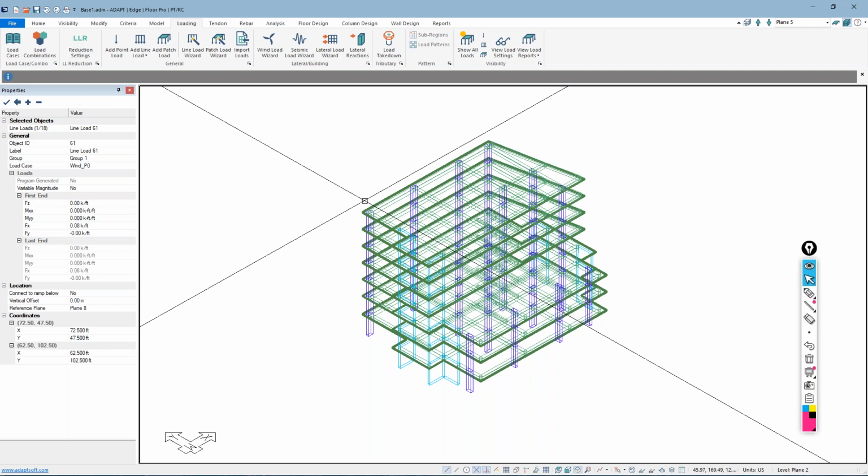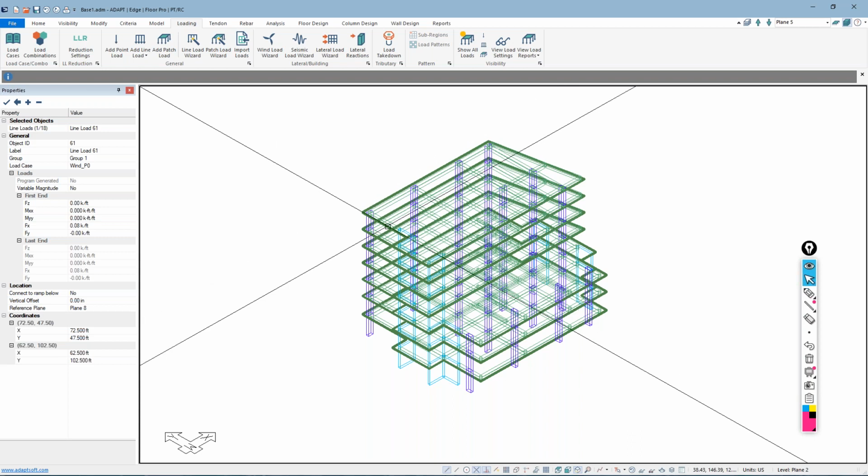Once you set up those modifiers, those are applied directly to the components that we use in the stiffness matrix, and they're adjusted for those modifiers. So we do produce cracked results for slabs and for beams, for horizontal floors.